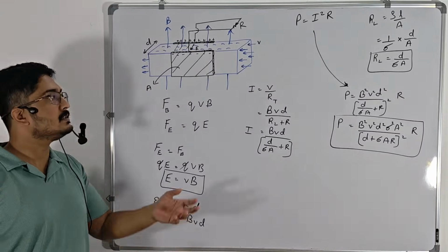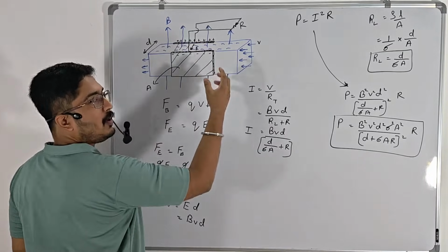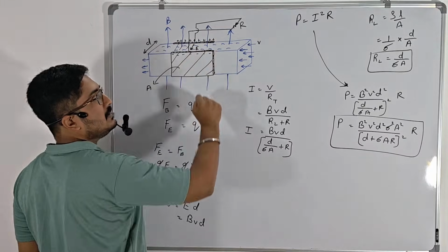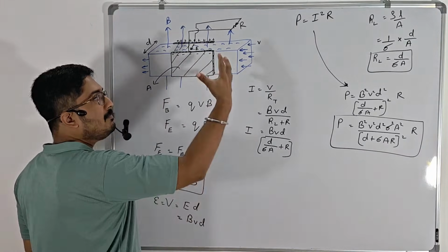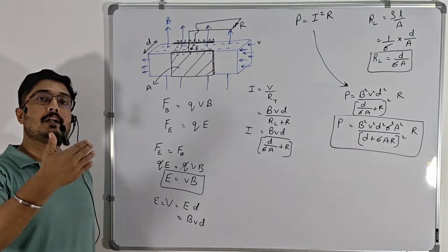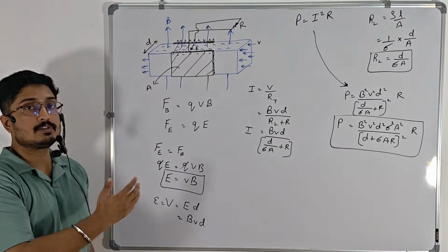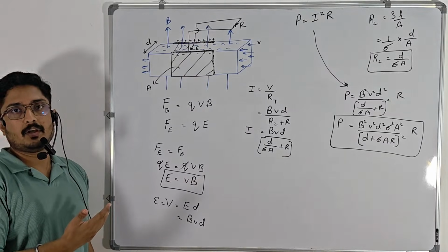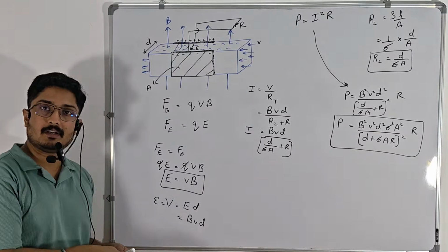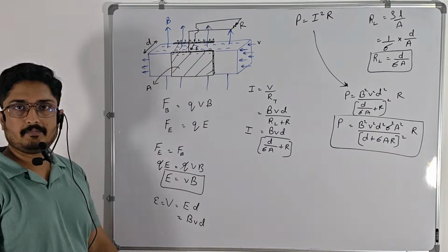Some entity is actually moving this fluid, right? See, when the fluid is moving in this direction, the fluid contains, let us say, positive charges. For example, I'm saying positive charges. Don't you think that the positive charges would be repelled by this positive? So there will be some repulsion experienced by these charges as it moves, right? To overcome that repulsion, you will have to provide some kind of mechanism like a pump to continuously move this liquid in there. So the motion of the liquid is maintained by a pump to which you are supplying some power. That power is now getting converted into electricity, which is later getting dissipated here as heat.